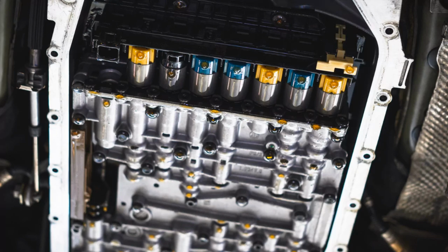This overloading allows for a slightly longer service life. However, the old solenoid still fails under the stress and hot oil, and soon needs to be completely replaced. By redistributing the load, the other solenoids are overloaded, and soon they fail. That is, the failure of one device starts a chain reaction.